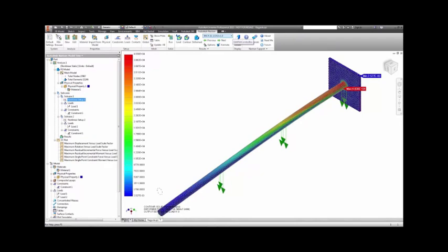After running the analysis, we get a deformation on the order of 7.25 inches. When we remove the load, we can see the pole is still bent, about 1.7 inches as a result of the material plasticity, with a stress of about 20,000 psi.